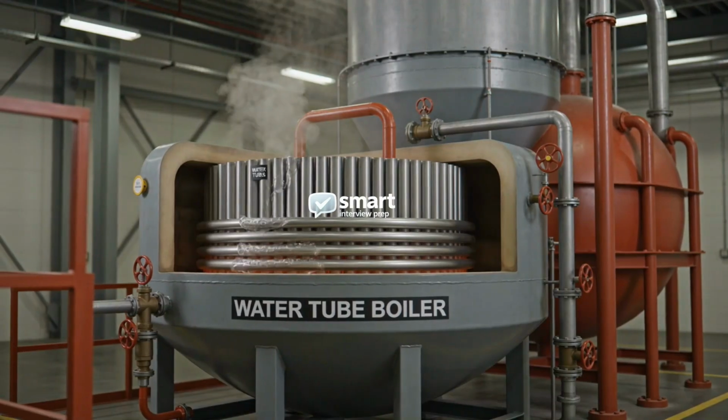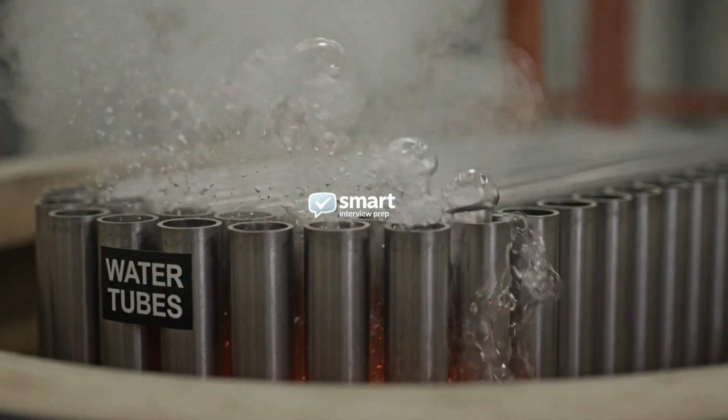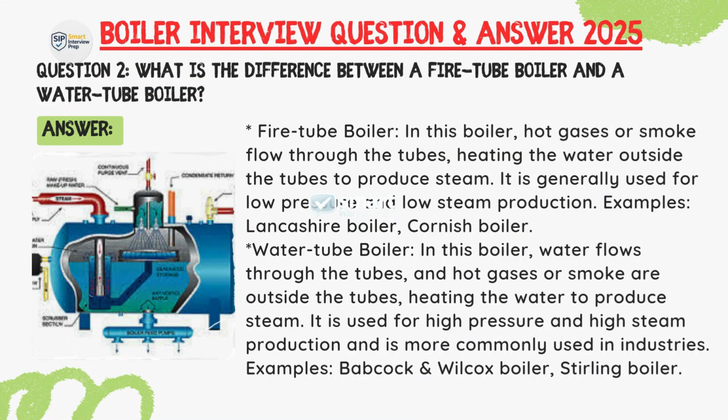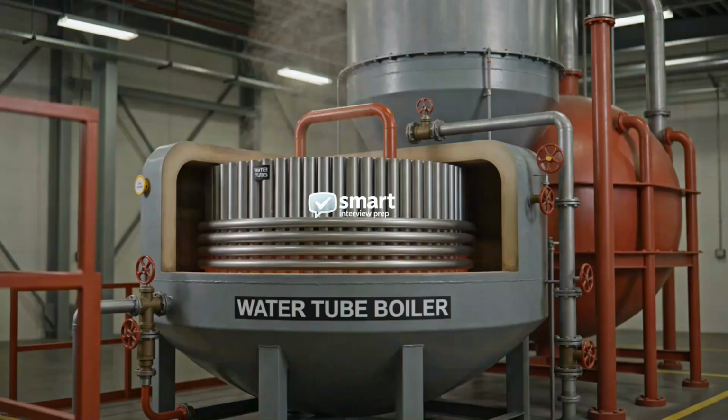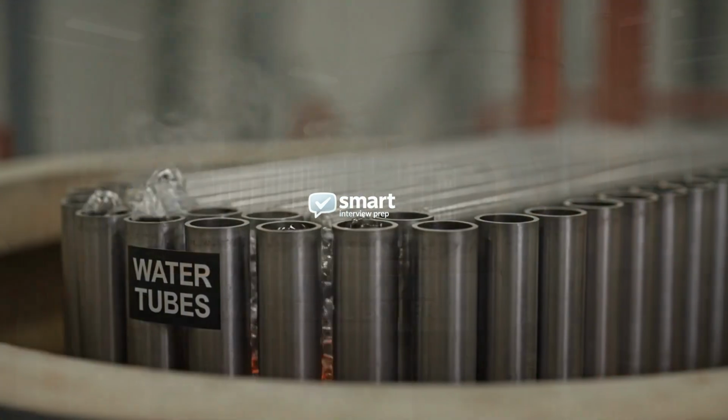On the other hand, water tube boiler, water flows through the tube and hot gases or smoke are outside the tube, heating the water to produce steam. It is used for high pressure and high steam production and is more commonly used in industry. Example: Babcock and Wilcox boiler.